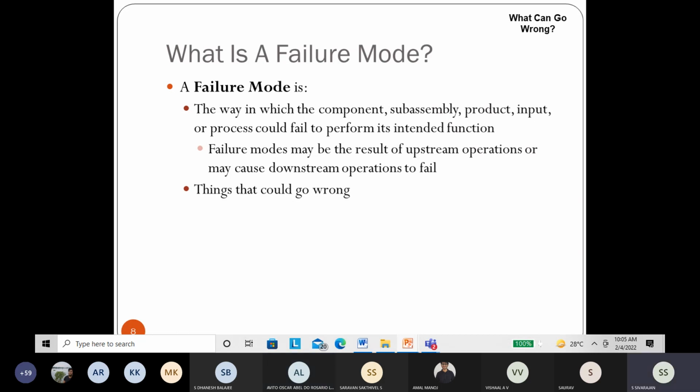No. For 1 inch, we have tolerance, ma'am. Many times, the hole size, whenever clamping is not proper, or when the machine is vibrating, the oversize will be more. So the idea is there is something called tolerance. You know very well, tolerance is a permissible variation. You need not manufacture exactly 25.4. It will be like this: 25.4 plus or minus 0.1. That means it can be 25.5 or it can be 25.3. So there is a range.